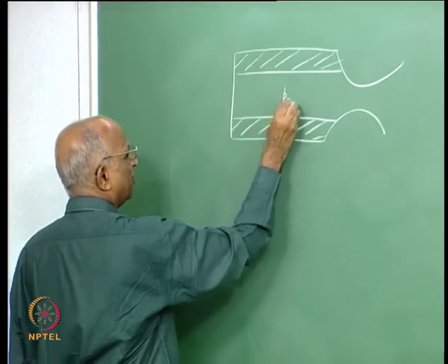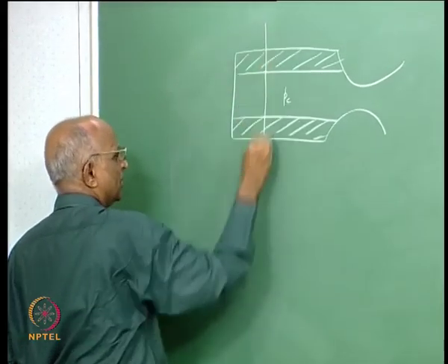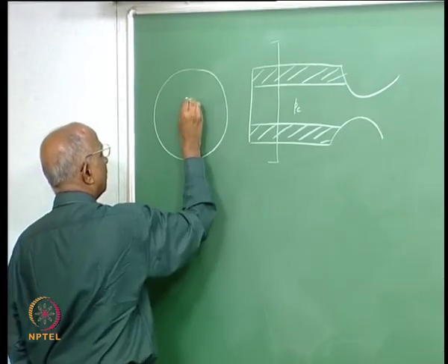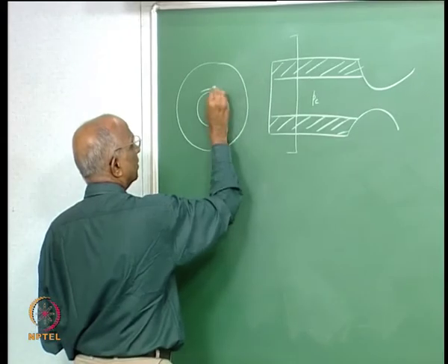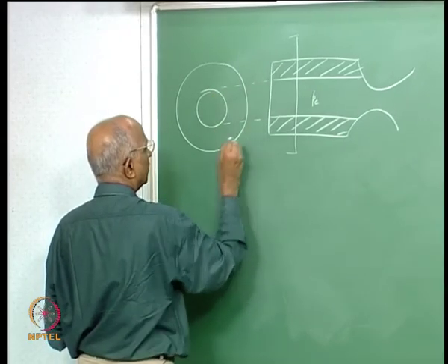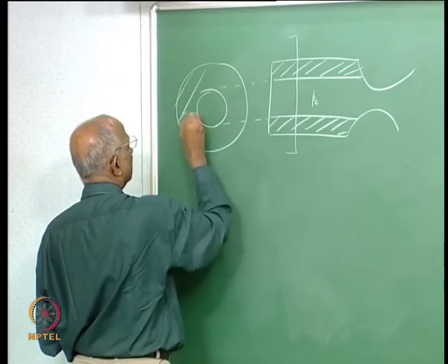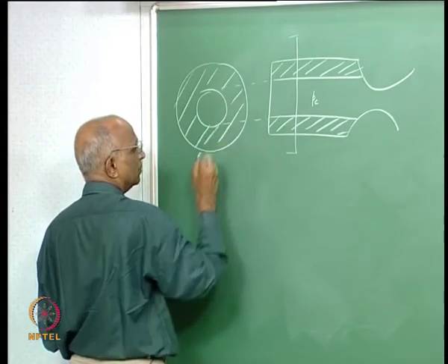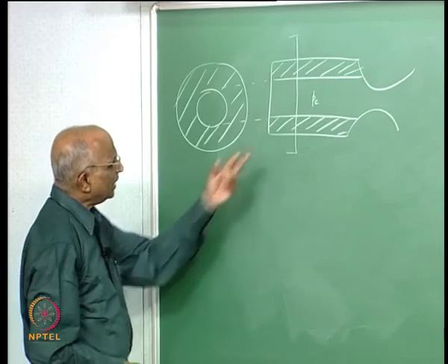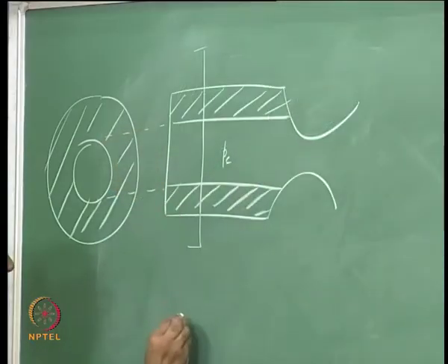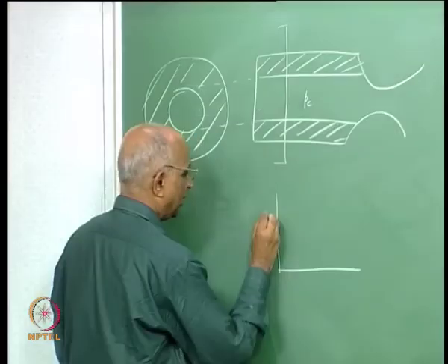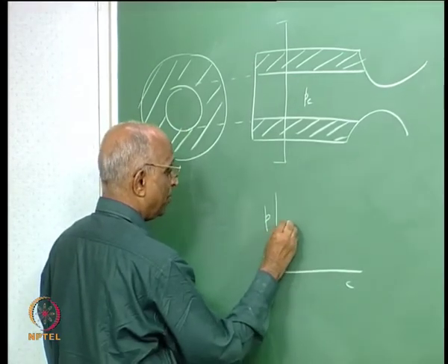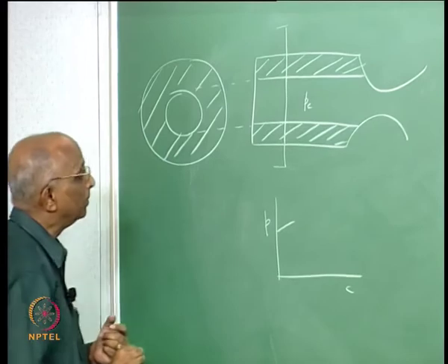Let the chamber pressure be Pc. This is, let us say, a section over here is the propellant grain, outer diameter. Let us say the chamber pressure is a high value, steady value burning, it is progressive, maybe it is going to go up, but it is a progressive steady value.